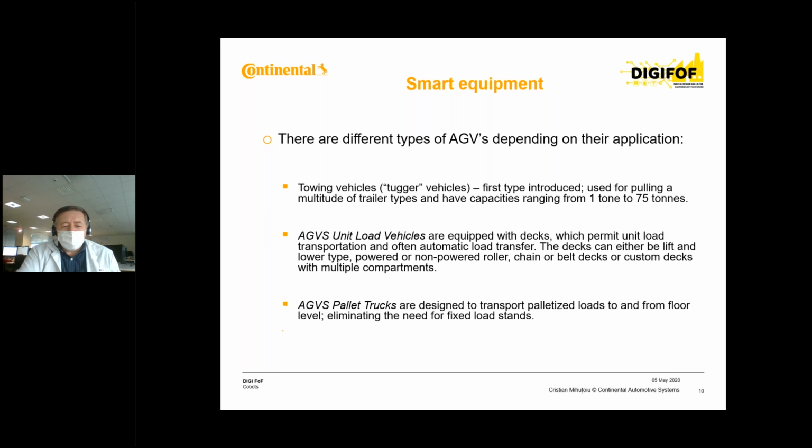Also, we have pallet trucks designed to transport palletized loads to and from floor level, eliminating the need for fixed load stands. So the AGV pallet truck is able to identify the pallet, lift it and transport it to a different location.